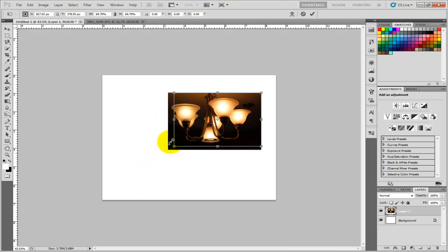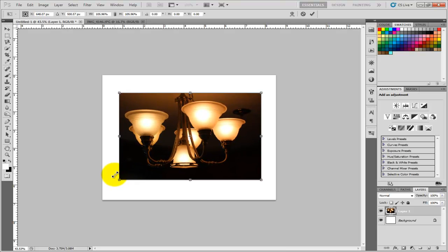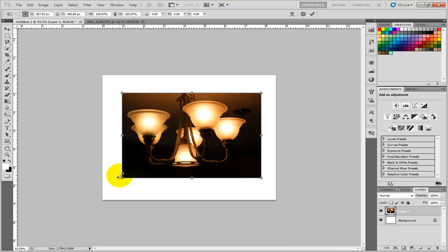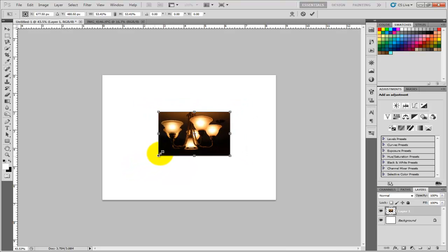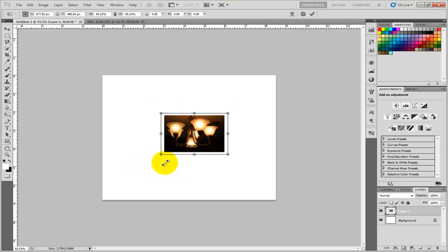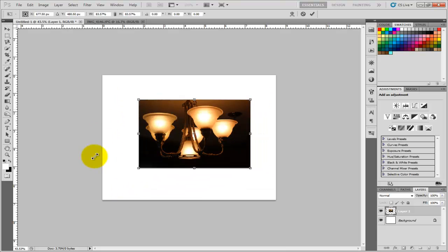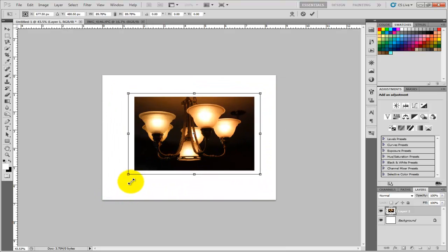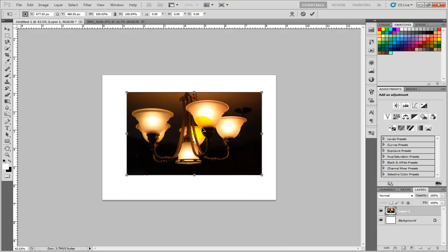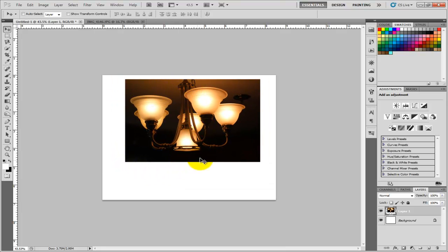Now let's say I had lined it up so that that center dot when I first started transforming was right where I wanted the photo. It's not really a problem. All you have to do is, while holding the Shift key, press the Alt key. When you hold the Alt key down and Shift, it's going to proportionately transform it with that little crosshair as the transform point. So it's going to all go around that. Alright, that's me holding the Shift and the Alt key. So again, I'm going to hit Enter, and it's going to get rid of the transform box for me.